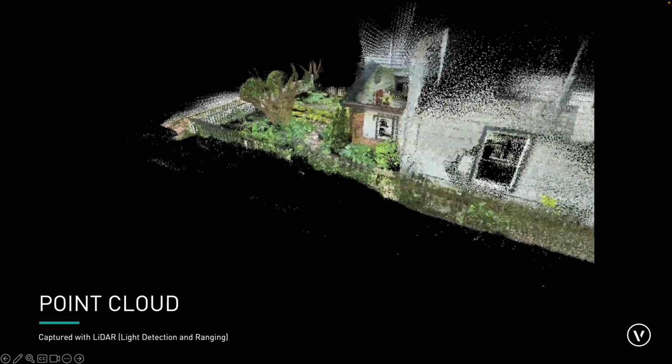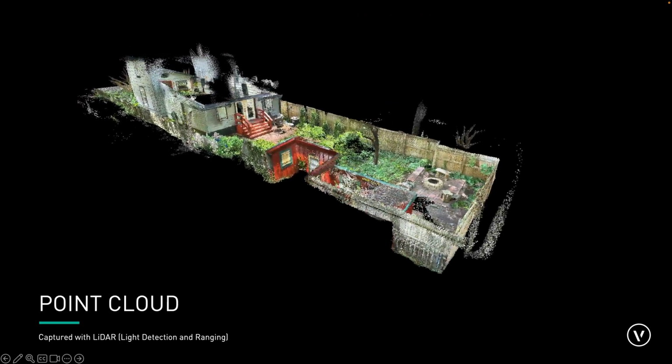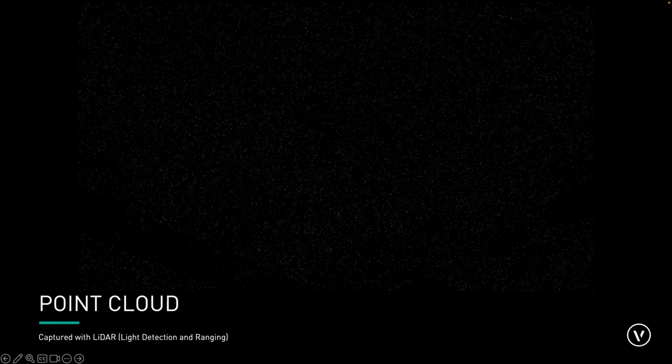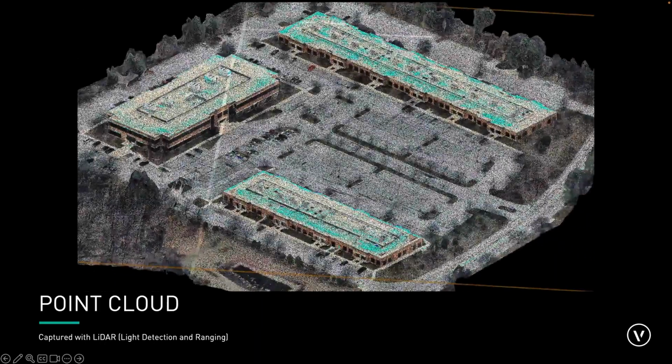Point clouds, on the other hand, are like digital representations of the real world in 3 dimensions. They are collections of thousands or sometimes even millions of individual points, each with X, Y, and Z coordinates that together create a detailed and accurate model of an object or an environment. They are produced using technology called LiDAR, light detection and ranging, which involves sending out laser beams and measuring how long it takes for the light to bounce back after hitting an object. By doing this millions of times per second, LiDAR can capture the precise distances to objects in its path.